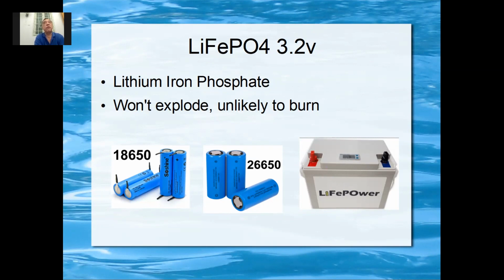Then when it comes to 48 volt, normally you take a lead acid battery, AGM battery, or deep cycle battery. All these are lead acid batteries. You need 48 volt, they will take the 12 volt and put 4 pieces of 12 volt together, then they get 48 volt. But in lithium battery, you normally should not connect them in series.